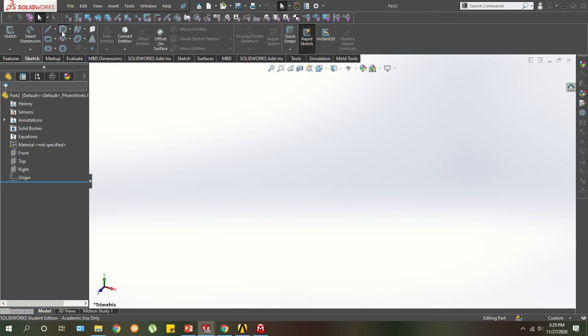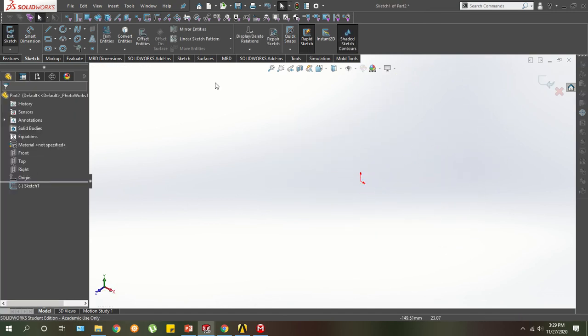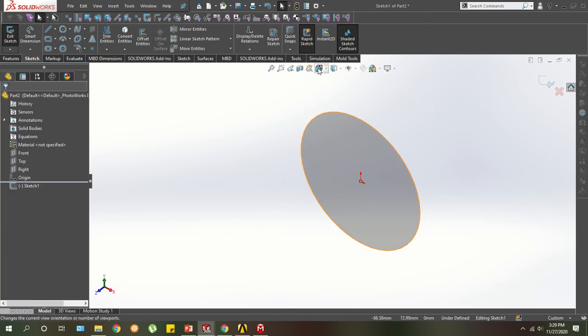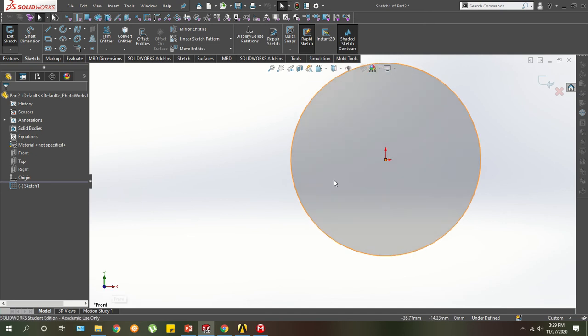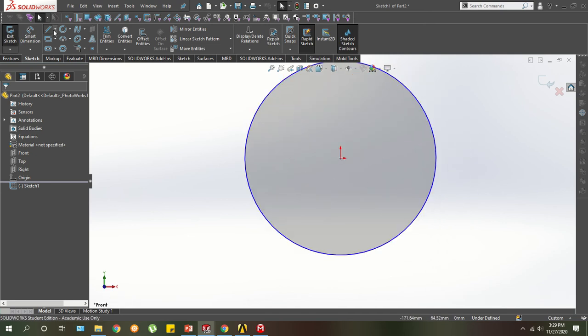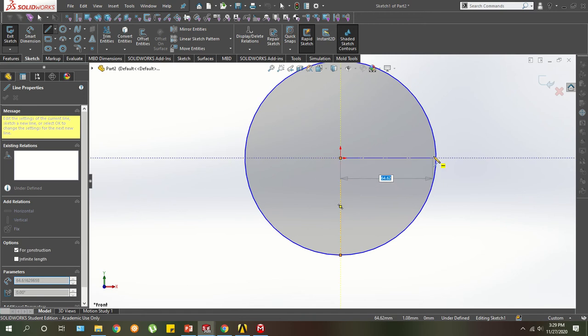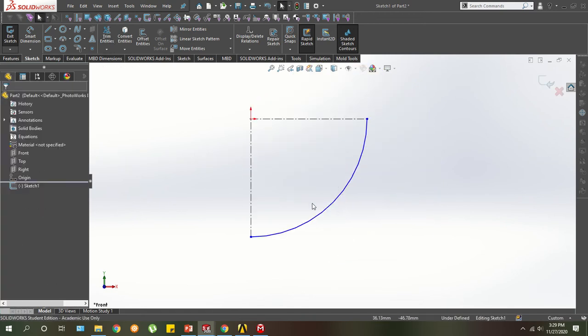And curvature basically just says, given a sort of curve radius, how many divisions do I need to model it accurately? I'll explain. So let's say you have a quarter circle. Let me just draw that out. All right, so let's say you have this quarter circle arc.